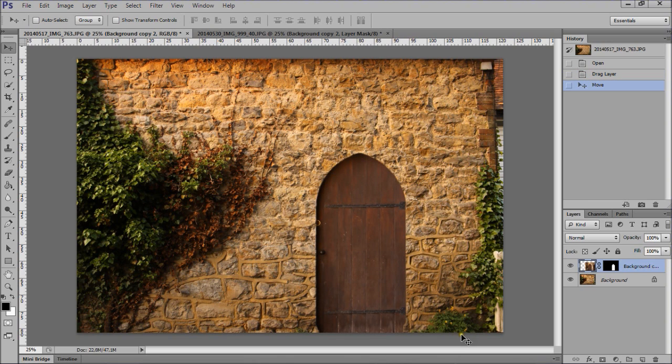And that's basically how the pen tool works. Quite effective for these types of shapes, I think, if you're trying to do sort of straight lines and regular curves. The pen tool is pretty good. You might try other methods for cutting out objects when you've got more irregular shapes and so on, but we can show you how to do that later.